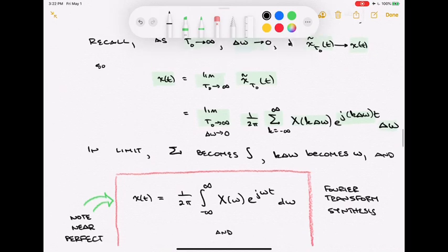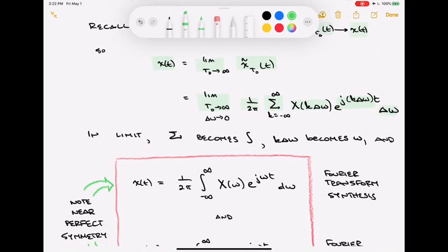And we can rewrite that expression now. And we write that expression as being our signal x of t, and that's the aperiodic one. And we were able to get that x of t back in because we related the underlying spectrum with those Fourier series coefficients, the x tildes. So our aperiodic signal x of t can be gotten as 1 over 2 pi, an integral from minus infinity to infinity of those Fourier transform coefficients, that underlying density function, that thing I said underlined all the samples that we looked at before, x of omega times e to the j omega t.